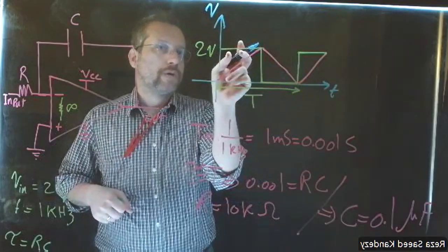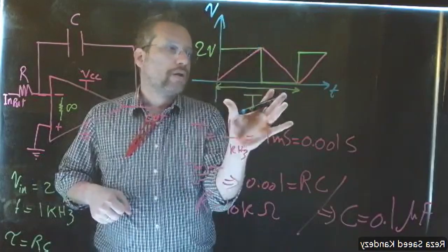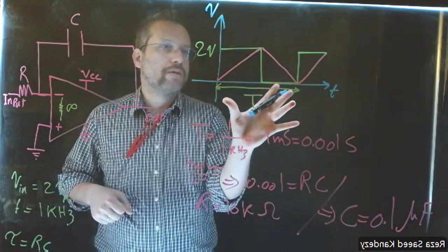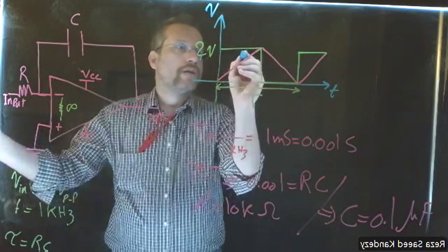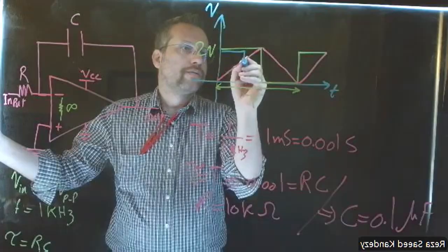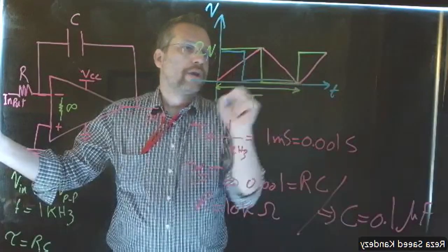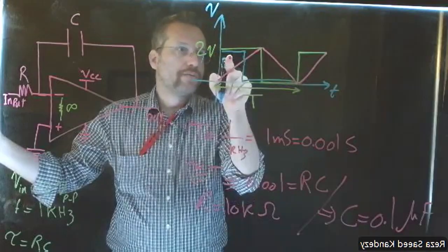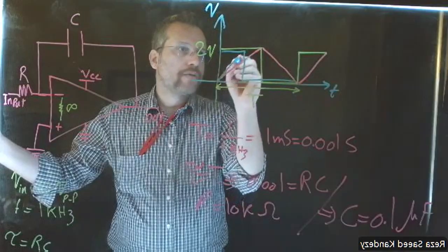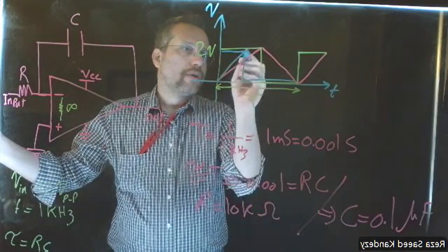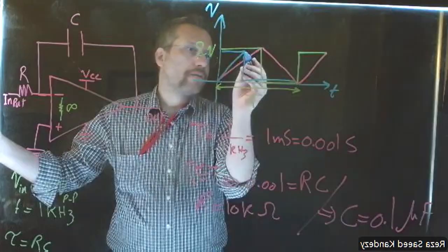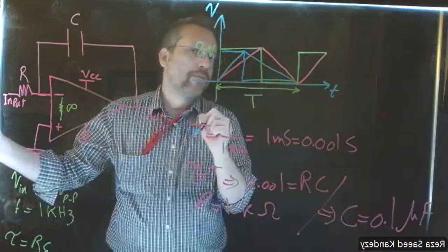Now you can imagine if I change the duty ratio of this square wave, meaning the percentage of the on time in respect to the whole one cycle time period. So let's say I chop the voltage earlier, lower duty ratio. What I expect from the integrator is a higher slope for the rising part of the triangle and a lower slope for the falling part.